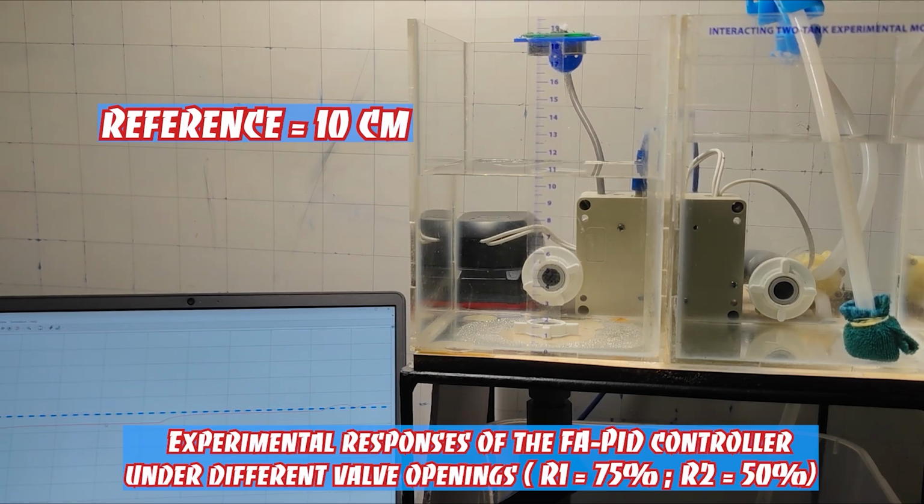This time, the system's nonlinearity becomes more apparent than in the previous experiment, resulting in higher signal delay and noise. You can see that the response shows some overshoot and oscillation but quickly stabilizes. Although the reference signal fluctuates around 0.3 centimeters, the system maintains high stability, demonstrating the effectiveness of the PID controller optimized by the Firefly algorithm.